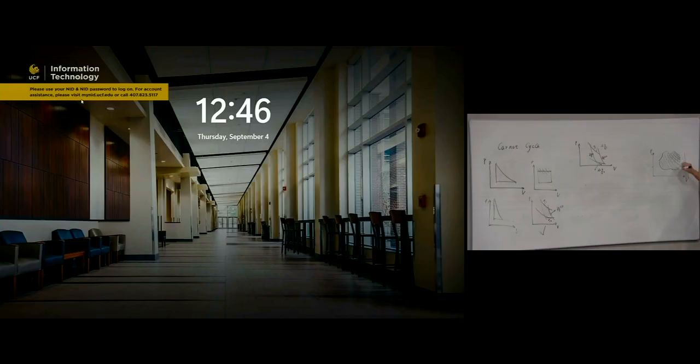And look at these two neighboring ones. So we have the Carnot cycle here. We have the Carnot cycle here. Right? They are neighboring to each other. And for that one, the cycle goes in this direction, and for this one, the cycle also goes in this direction. Correct? But on the shared edge, for the upper cycle, the process goes in this direction, and for the lower one, the cycle goes in this direction. They cancel each other. Right? And eventually, you only have this kind of envelope. Right? Because the contributions of all these tiny Carnot cycles just cancel each other.